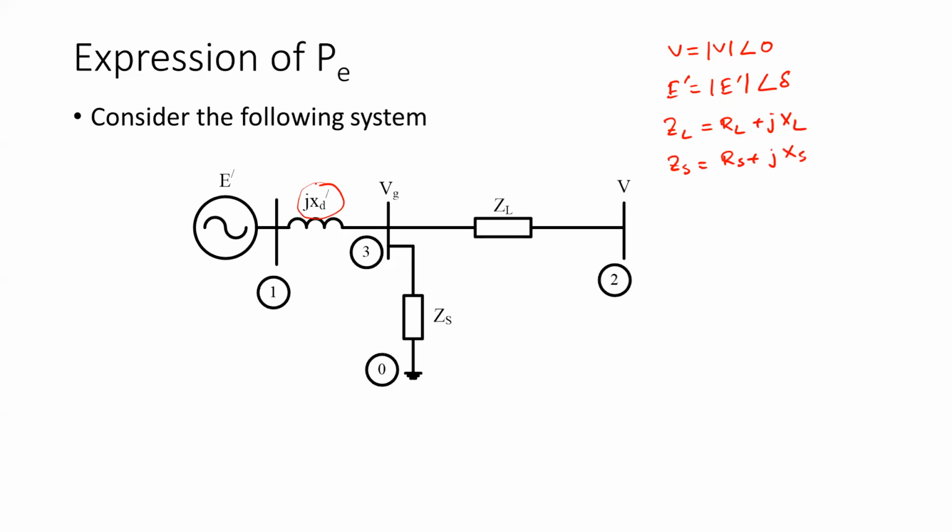So that's fine. How many terminals do we have? Or how many buses? No, it should be terminal actually. Let's be more specific: how many nodes do we have? 4. 3. 3, sir. 3 or 4? Sir, 4. It will be 4, because 0 is your reference node again. So we need a reference node. Then you have your node 1, and the rest are marked node 2 and node 3.